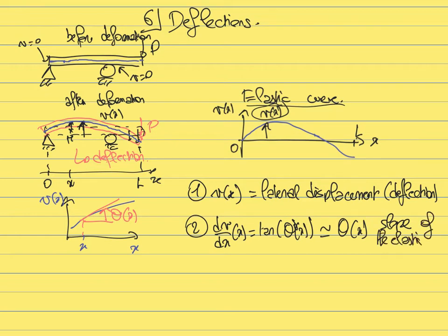Because in certain cases, for example, if you have a beam that is attached to a fixed support like this, then necessarily, because the fixed support prevents the rotation of the beam at the point at which it is attached, the slope is going to be 0 at this point because the beam is attached to the fixed support and cannot rotate. So the slope is also going to be an important feature that describes the deflection of a beam subjected to bending.